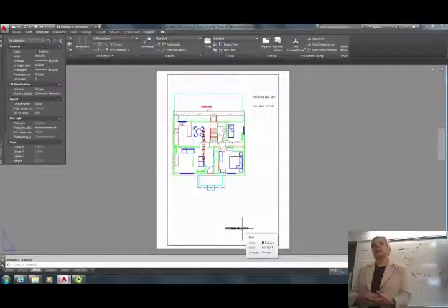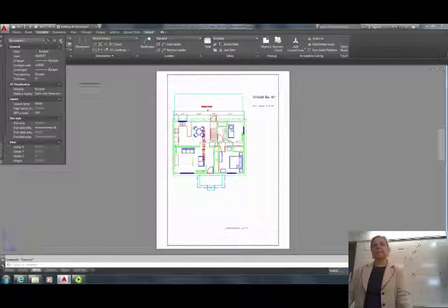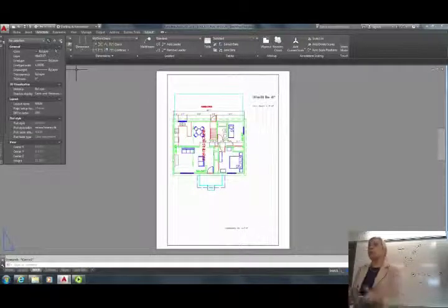Basically in model space, it's like you take a big paintbrush and you have to paint your note on the grass of a big house. And if you're going to reduce it 96 times, you're going to reduce the text as well. So that's text in controlling it by doing what we just did.